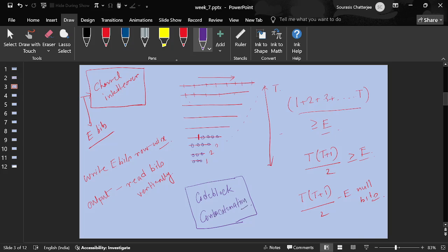And one thing, the code block concatenation output can be odd, right? But on the receiver side we again need to do deconcatenation, so the number should be even. So how do we address this? By adding zero in between. Yeah, again zero padding is our way out. Fine.